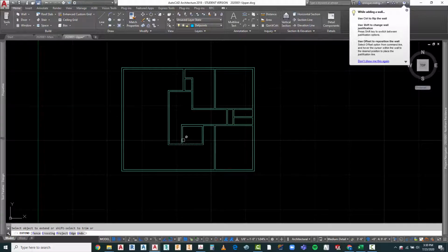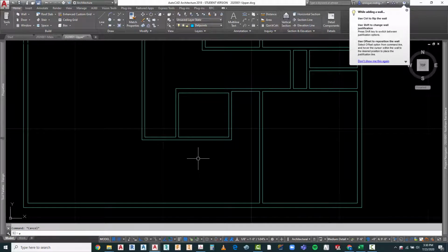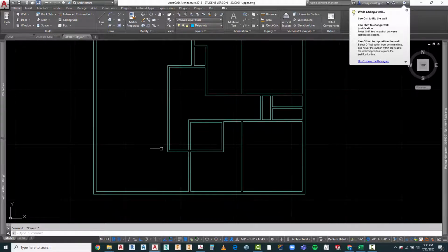So as we develop these drawings, you'll see what I'm talking about. I'm going to go ahead and extend this wall to there. This is going to be where the tub is. There's going to be a large fiberglass spa located right in there. I've got a location here for the closet. There's two dimensions that they're guiding me by. One is 10 feet here. So I'm going to take this line right here.